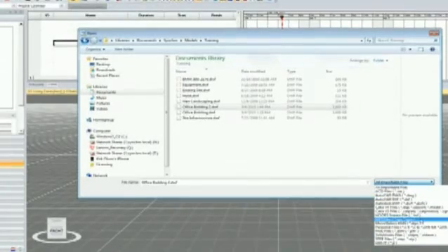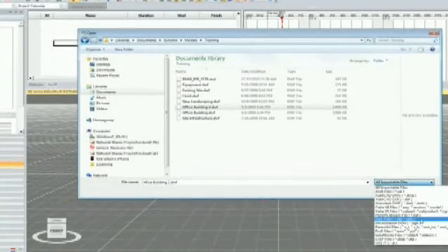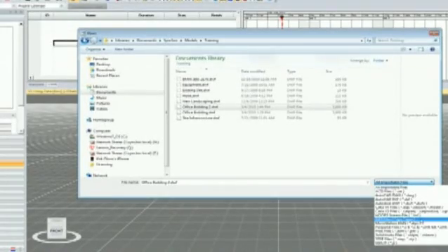So either you work in SketchUp, publish it out as a DWG, and import it into Synchro, but the best way to do it is to download our 32-bit version of the software and import SketchUp directly into Synchro in a 32-bit mode, because it imports better in SKP versus a DWG. Okay, any questions on file imports? We also have all the AutoCAD object